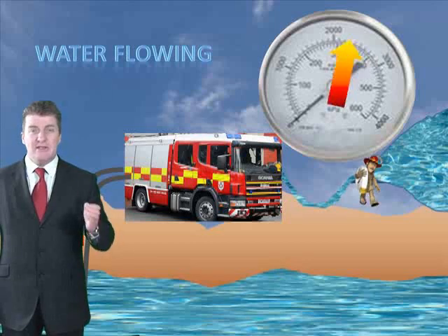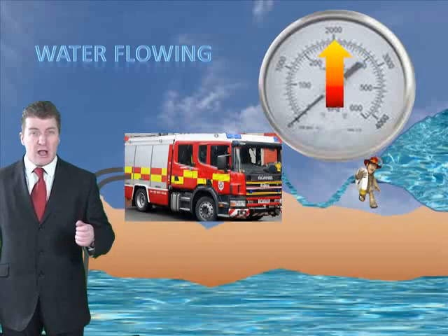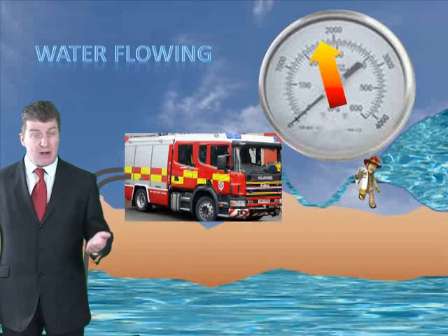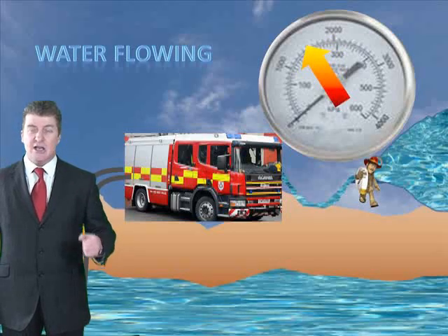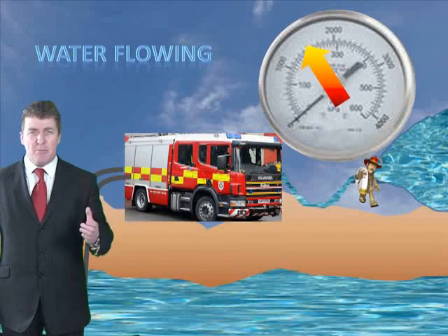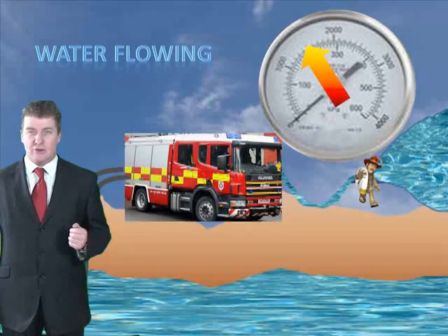Now as you open the delivery and let water flow, the pressure will drop as this pressure energy is converted to velocity energy at the nozzle. So as you can see, the pump converts velocity energy to pressure energy, and then this is released back to velocity energy when water flows back through the hoses.